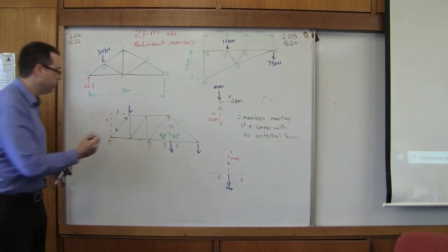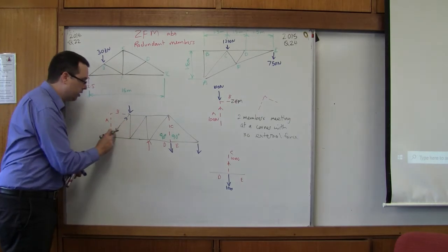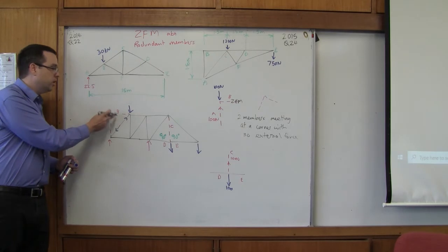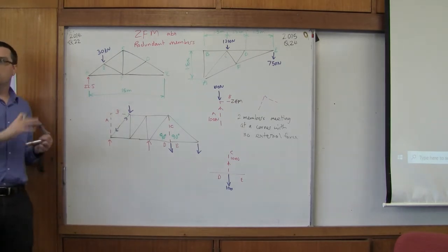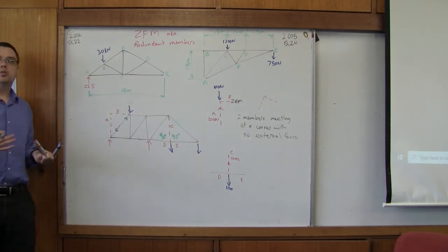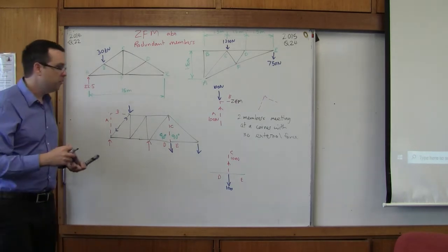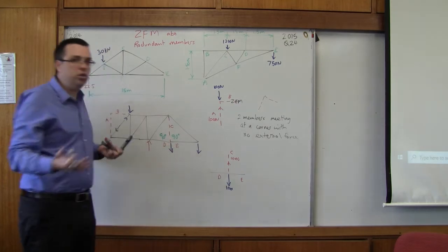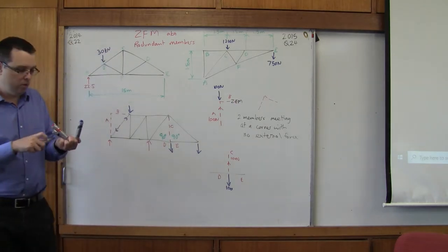I think I maybe misspoke, but you get the idea. So that's going to have to be what balances. A can't do it, because if A has any amount of force, B can't resolve it, B can't keep it in equilibrium. If B can't resist it, the thing's going to explode. Same thing here, right? If C has any amount of force, D and E just don't have any vertical components, so they can't keep it in equilibrium.